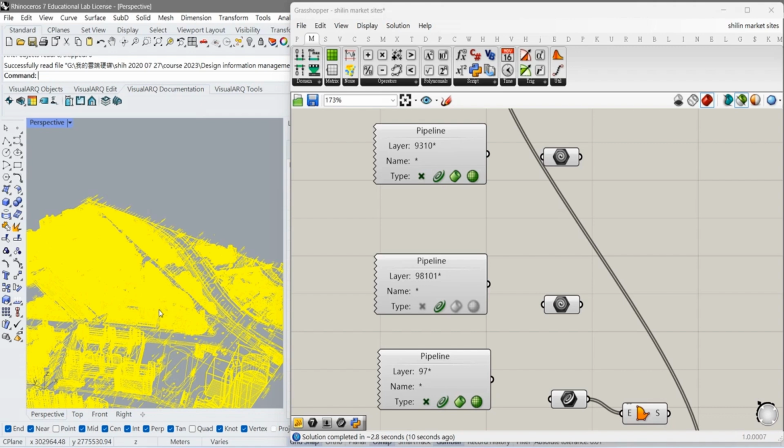Can be divided into many lines. No, developable means you can use a sheet of paper to cover it precisely. You think this is developable? Okay, first, of course, it's a ruled surface because it follows straight edges. And what is the condition for this ruled surface to be developable?